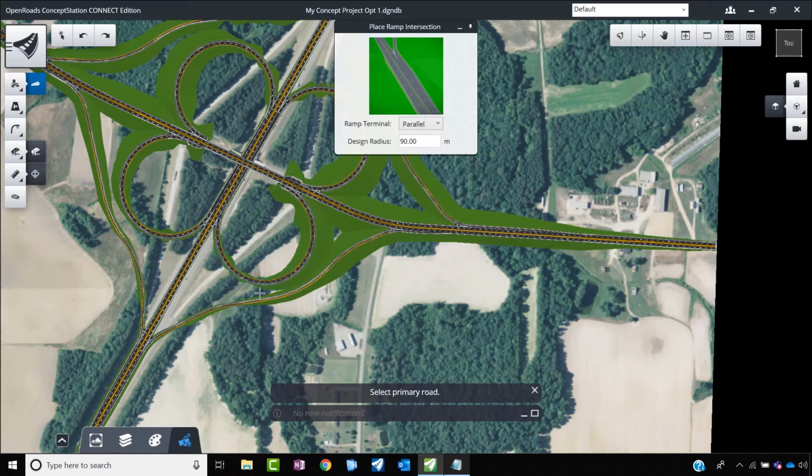If there is a lot of fill, you could review with various options. Save this DGN database as a separate one. Save as a file with a different option. Open that file up and you could make changes by creating this bridge and you could review with respect to your cost estimates.